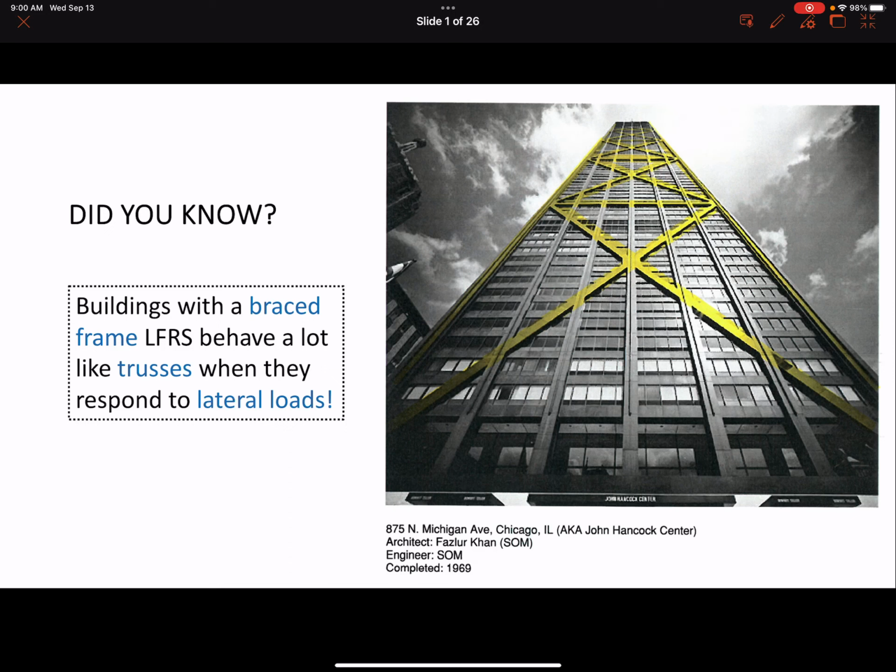One interesting thing to keep in mind as a structural engineer is that we just talked about trusses, right? And so we know that trusses transfer forces primarily through axial behavior. Those truss members are either in tension or compression. You don't really consider shear or moment when we're designing truss members. Sometimes we may have some shear and moment in the top and bottom chord members, but usually that is very minimal compared to the magnitude of the axial forces that they carry.